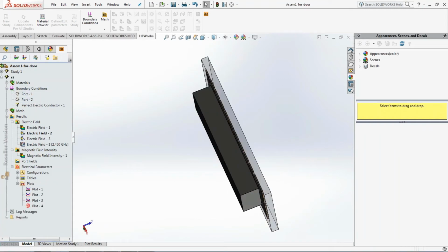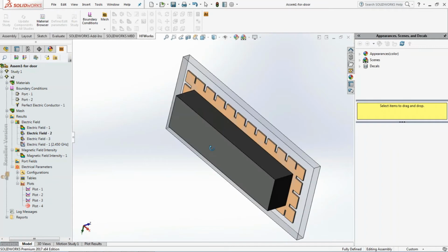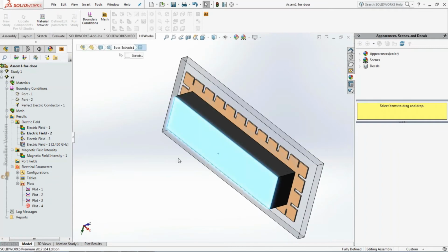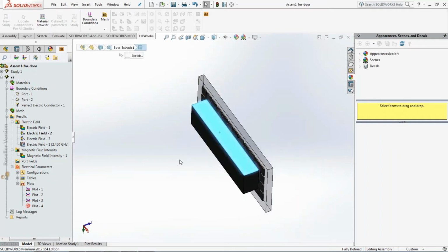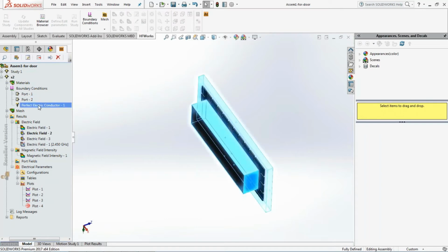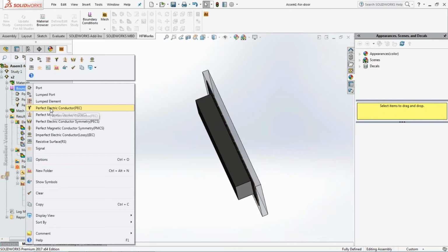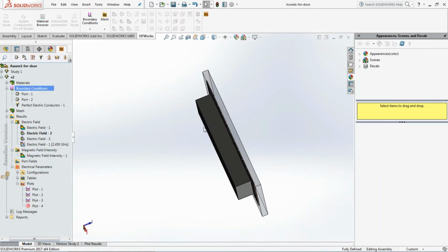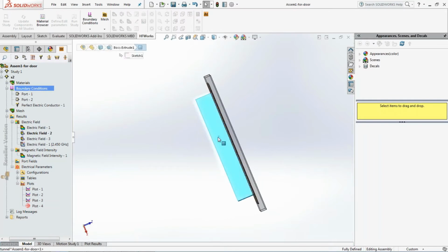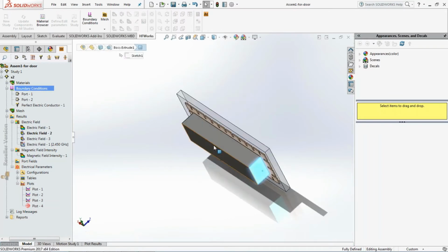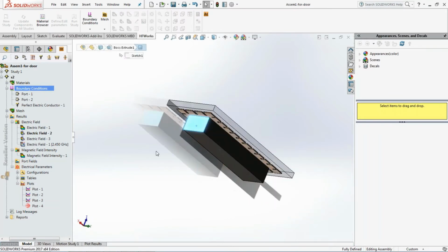Here, we imagine that here is going to be our port where our microwave is coming in, because it's going to be our microwave cavity. I choose PEC, perfect electric conductor, to be my boundary conditions for the body of my microwave cavity, right?